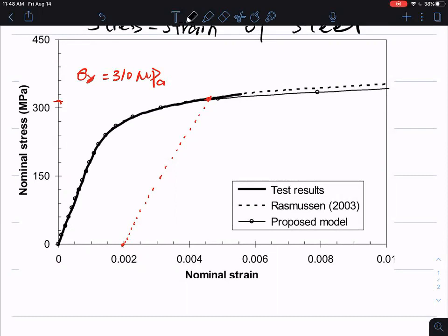That's kind of passing the elastic region. For elastic, you need to look at where the linear region of this curve is. You can't totally read this, and the point is a little bit tricky, but I think the linear region stops somewhere around there. So if you apply a stress larger than that level, you're going to have plastic deformation. If you apply a stress lower than that point, you can have elastic deformation.